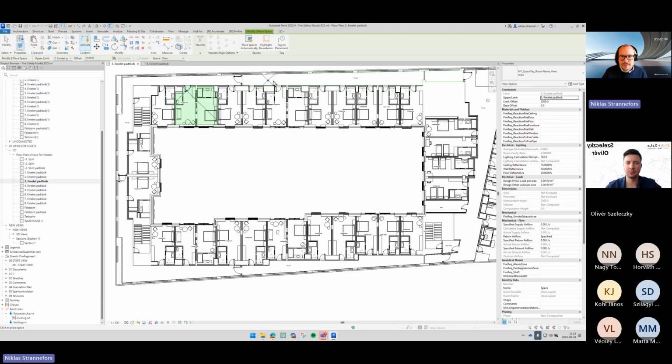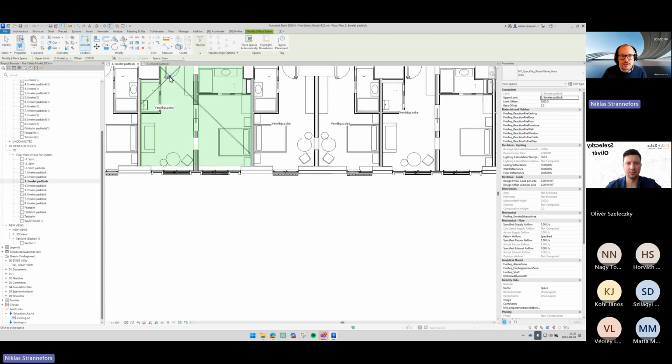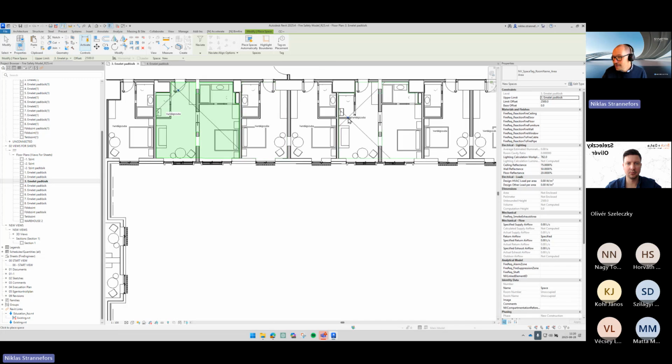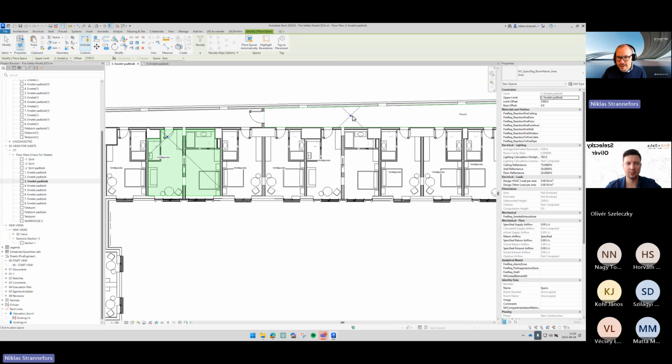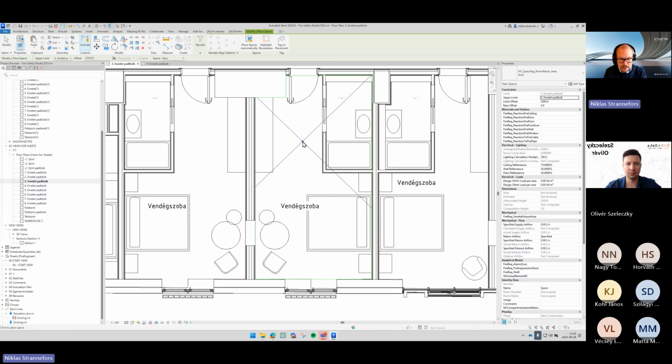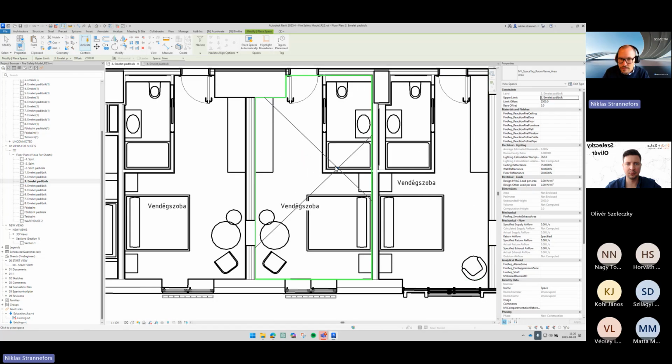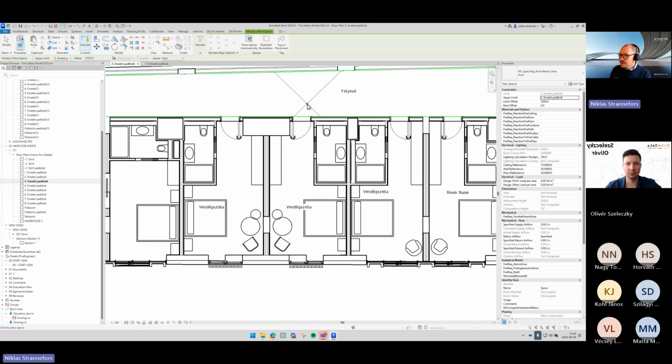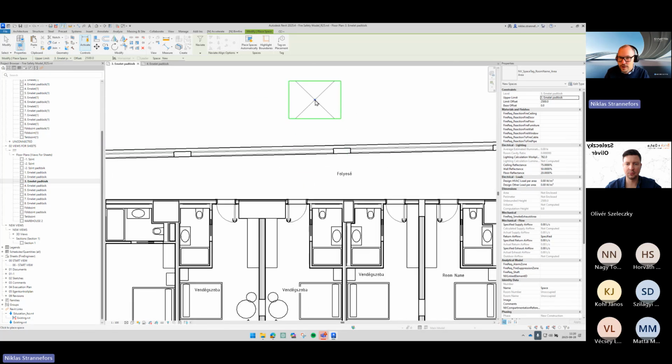If you hover inside, which is super strange that the architect has placed a space there because they shouldn't, you can see that it finds all those walls. You can see a green boundary around the rooms when we move our cursor. This works because we made the link room bounding. If you forgot to make the room bounding, it will look like this outside. If I move the cursor outside, you get a red rectangle indicating it can't find walls to bound the different spaces.